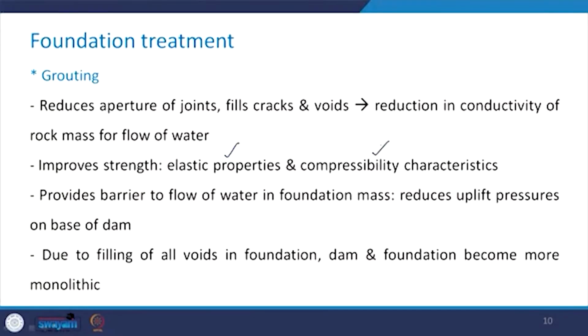So, this reduces the aperture of joints, it fills cracks and the voids and results in the reduction in the conductivity of rock mass for the flow of water. Plus, it improves the strength by improving the elastic properties and the compressibility characteristics.